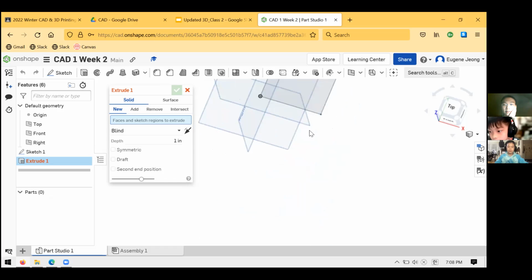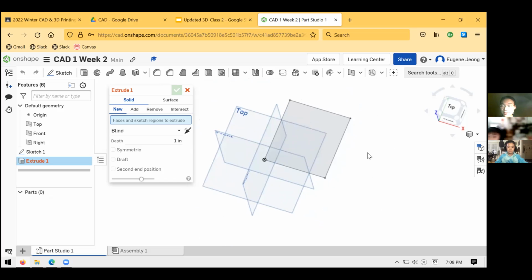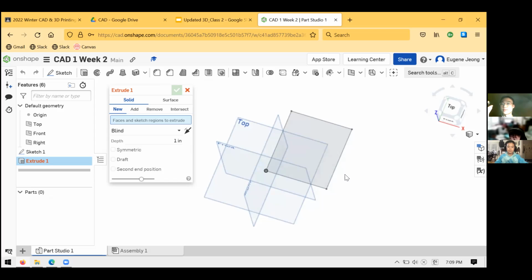So right now you're looking at it like this. If you middle mouse and just drag down, it'll bring everything down a bit. And hopefully that works. I believe there's an alternative command you can use. Yeah, the alternative, if you for some reason don't have a middle mouse, is control right click. So if you hold control, then also hold right click, then move your mouse around. That does the same thing. So if you don't have a mouse, or your mouse doesn't have an M3, then you can just do that.